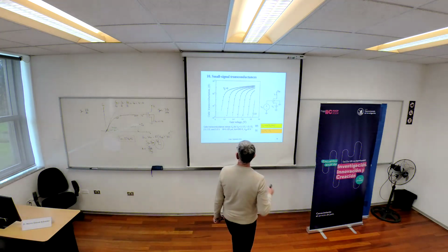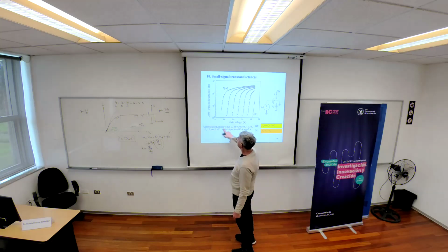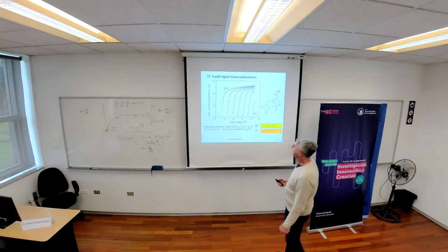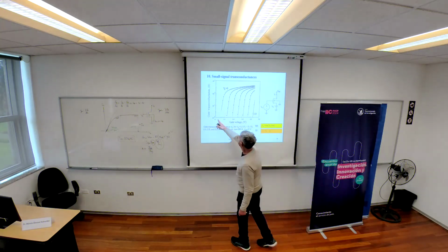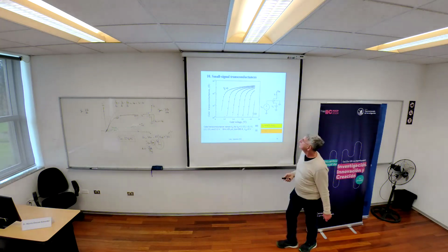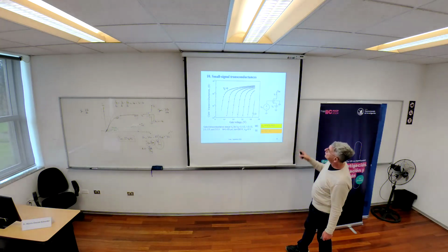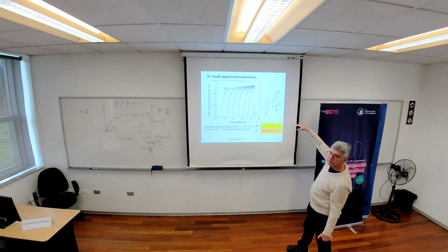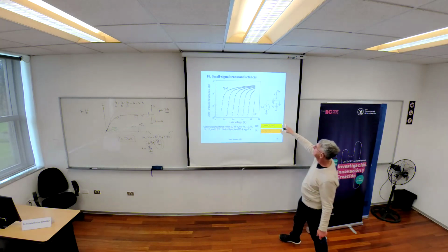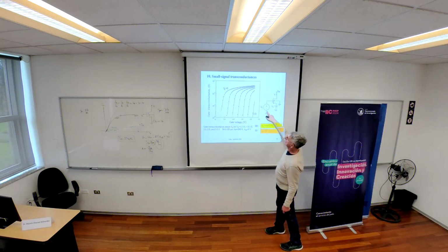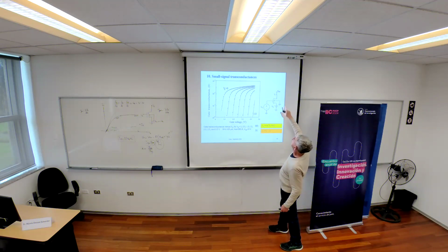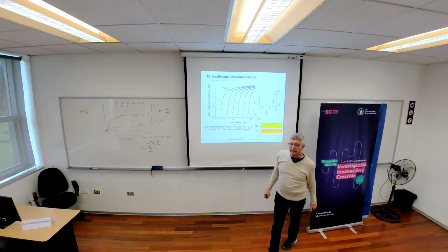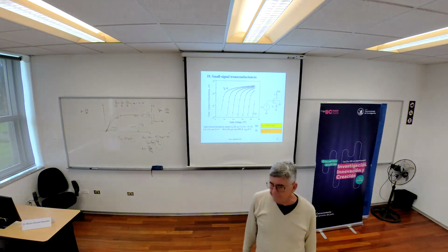This picture represents the gate transconductance for several values of Vs, and this axis is the gate voltage. The circuit used to measure this characteristic is this one here. You change Vg. There is a switch in Vg. In this case, the drain connects to the power supply.